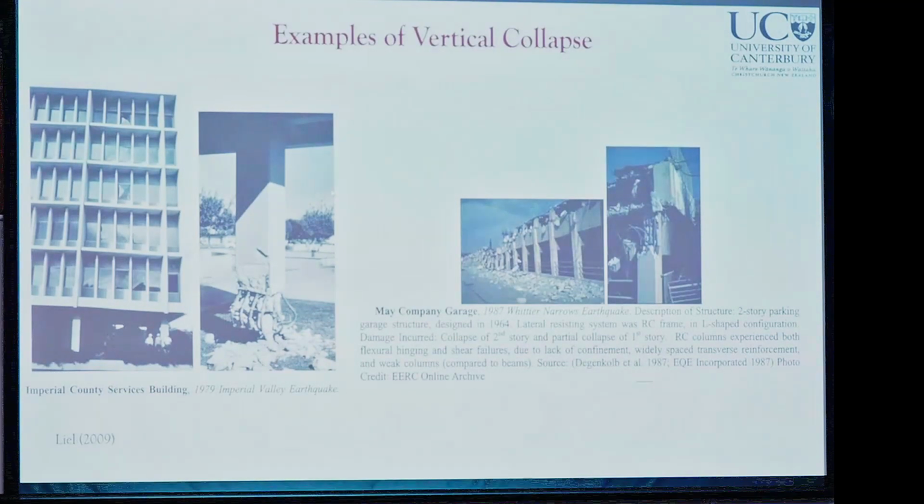One thing that I need to add is that with the sideways mode of collapse, we see complete crushing of the building. There's nothing left, and the building has completely collapsed normally. Whereas with the vertical collapse, we might have the collapse or failure of some components. And if those components are important, for example, like this column in this building, that results in complete damage of the building, and the building is not repairable after the earthquake, and we will probably also have some injuries or maybe death.